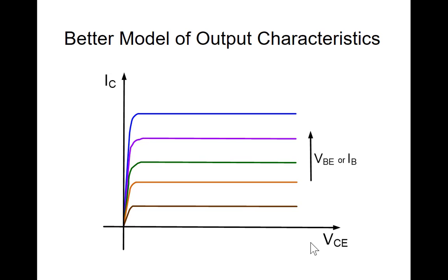So then, could you also use a MOS transistor as a current amplifier? No, because you would need the BJT for it. We could trick a MOS transistor to act like a current amplifier as well. We'll talk about circuits that do that later, but there's no current that flows into the gate. So you can't amplify a current that doesn't flow. Or you could think of a MOS transistor as having infinite current gain if you wanted to.